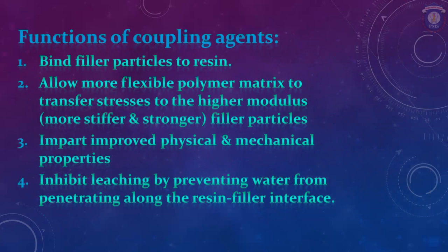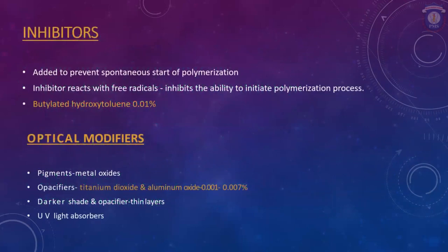It allows the more flexible polymer matrix to transfer stresses to the higher modulus filler particles. It imparts improved physical and mechanical properties. It inhibits leaching by preventing water from penetrating along the resin filler interface.